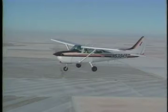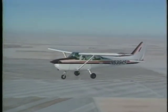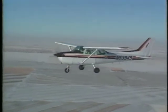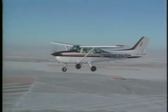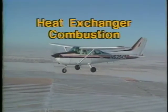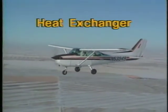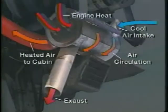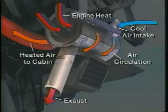For winter flights or flights in colder temperatures, a cabin heater is often more essential than an air conditioner. There are two basic types of heaters: the heat exchanger and the combustion type. The first one we'll discuss is the heat exchanger, which is commonly found on single-engine airplanes. These systems pass cool ambient air through a shroud surrounding a hot component in the engine compartment, usually the exhaust system. This heats the air, which is then vented to the cabin.